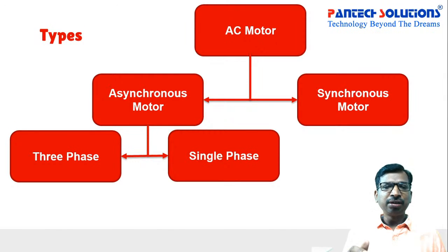So due to that, again we can get a mutual inductance on the rotor side, and due to that we can run the machine with the same principle. Again, in the three-phase system, by default three voltages are available, each 120 degrees apart. Finally, we will get a resultant flux. Due to that resultant flux, the motor will start to rotate by the mutual induction principle.